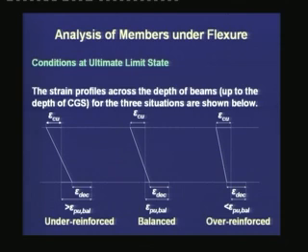For the profile at the left, at ultimate the strain of the extreme concrete fiber is epsilon Cu, and the strain in the prestressing steel is higher than the strain for balance. Here we can see that the linear strain diagram comes from the assumption that plane sections remain plane till the failure, and next we have to also note the strain compatibility condition at the level of the prestressing steel. Here there is a difference between reinforced concrete and prestressed concrete.